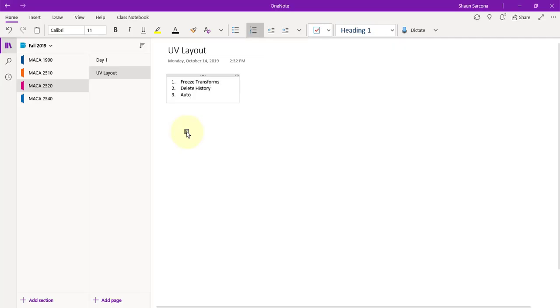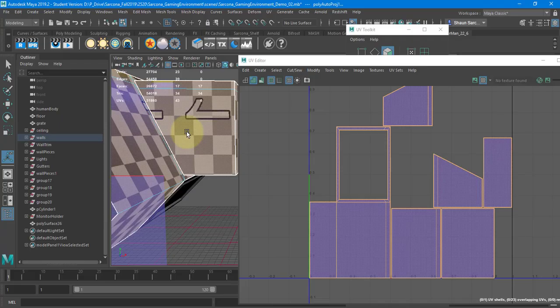So then I'm going to automatic mapping. Okay, so they are stretched out on the projector. On my screen, they are not stretched out. So just squish everything with your eyes about 5%, I think, and that should be good. So that is laid out, okay? So as far as UVs go, this would work, okay? For that one shape, this whole thing of just going to automatic will work.